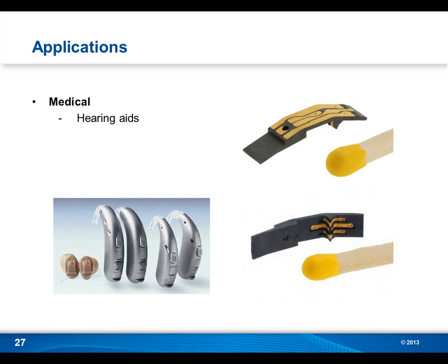Gotcha. And then Don, I know that you have talked about the through-hole plating on this part. So talk a little bit about plating vias when you're working with an LDS part. One of the questions we get often about LDS is, can you do multi-layer? Because of the nature of it, you can't really do true multi-layer. But one of the ways you achieve this is by using front and back planes. So this part has a molded through hole. The through hole is actually part of the mold, the edges of the through hole are activated with the laser direct structuring process, and it's plated through, so you get a front to back connection on this part.